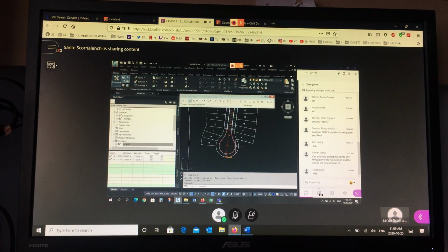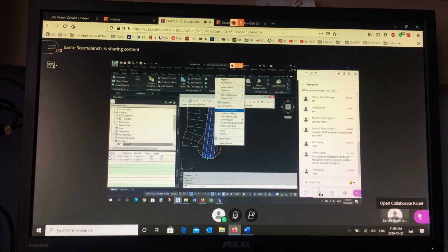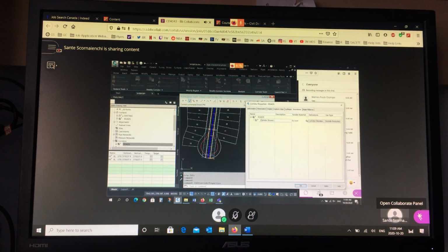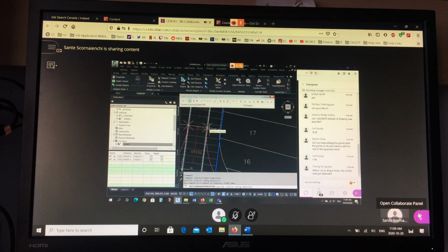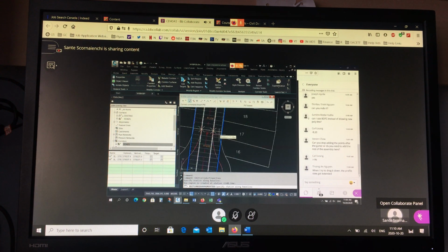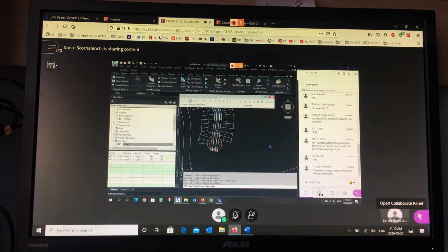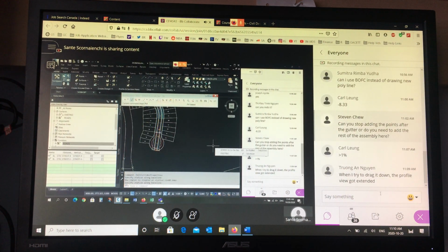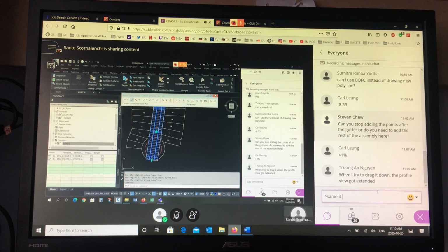Another way of doing it is going to the corridor properties, go to that parameter, the last region, this one here, the last one. I'm going to split it again, so instead of 3 pieces there'll be 4, so split the region. Where do you split it? Exactly at the entrance. Click here. When you're splitting the region, as soon as you're done picking your split points, say OK and let this rebuild. Don't make any changes until you let that whole process complete itself, and then you can go back and change it. So now you can see we have another split here.